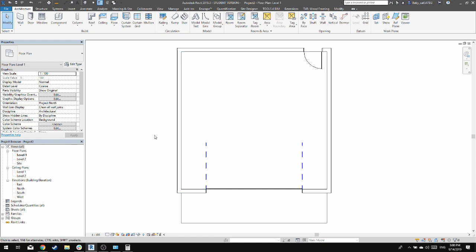So now we are at the point where we'll have to change views, and I'm thinking now would be a good time to go into the 3D view to see how the model is looking. Because I personally believe that going between two-dimensional plan views and elevations and the 3D view allows for a greater level of detail and understanding of the design. So we can go up to this uppermost ribbon and click on the little house icon to open the default 3D view,